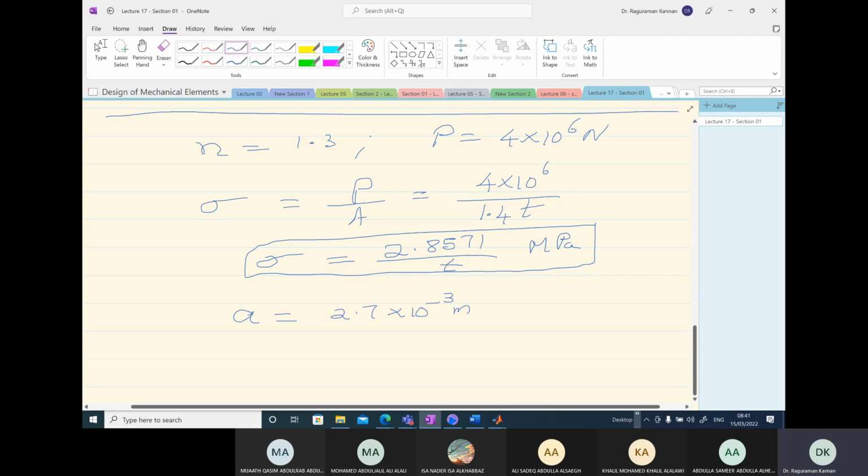We have to use this value. So first, since the crack is present, the quantity I will calculate is the K I value. K I is the stress intensity factor, and the formula we have seen before is beta sigma root pi a, and it should be in megapascal root meter.